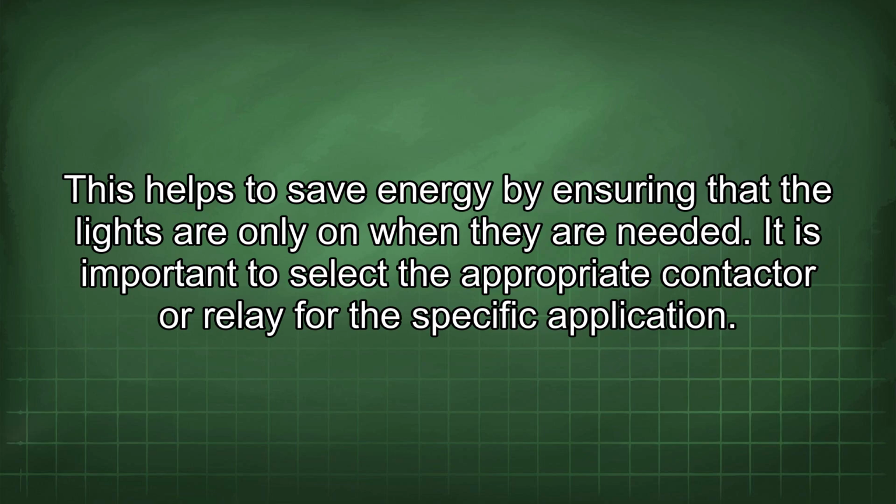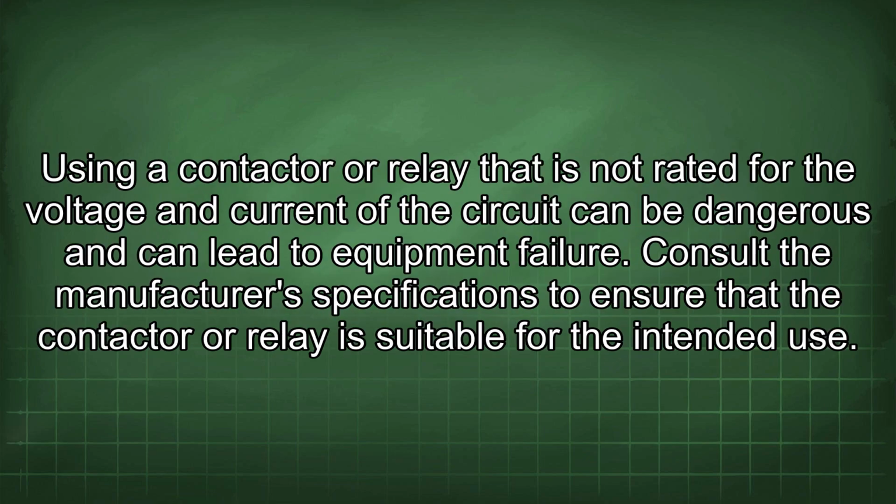It is important to select the appropriate contactor or relay for the specific application. Using a contactor or relay that is not rated for the voltage and current of the circuit can be dangerous and can lead to equipment failure. Consult the manufacturer's specifications to ensure that the contactor or relay is suitable for the intended use.